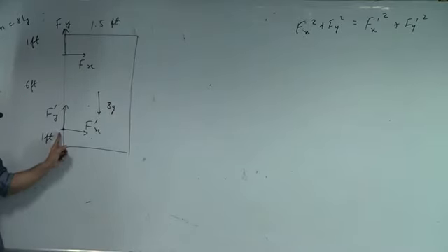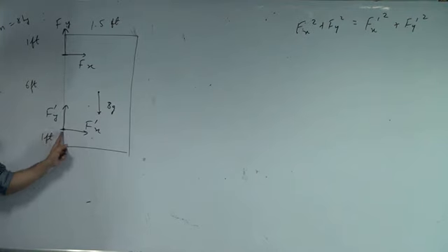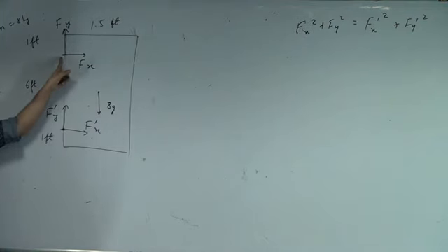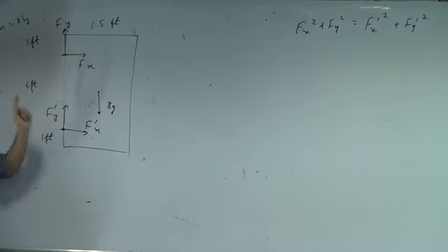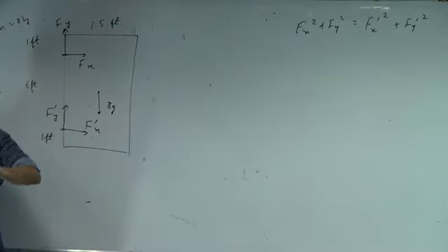Is that correct? Okay. What is the torque of the weight? What is the torque of the weight? Yes, the direction. The torque of the weight is clockwise. That torque will be balanced by the torque of this hinge force. Tell me what will be the torque due to Fy. Think and tell me. The torque of Fy, this is the axis I'm choosing. This is the point about which I'm calculating torque. 0, excellent. Fy, 0, correct? Now which torque can balance it?